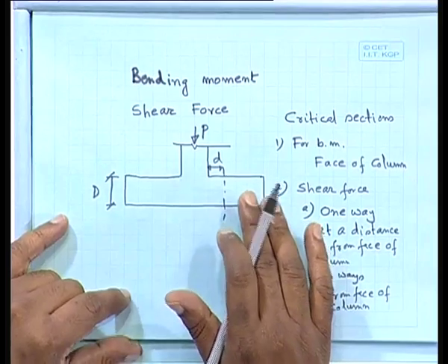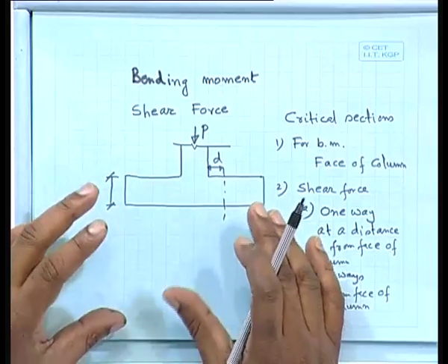We could do it, but we do not want to do it here. So, the only alternative you have is to increase the depth, so that the shear stress developed is less than 0.35 Newton per square millimeter. So, we have to start with one of them and then you have to check.